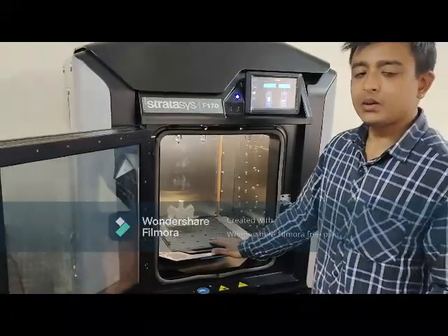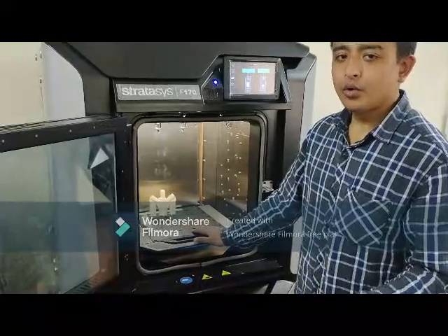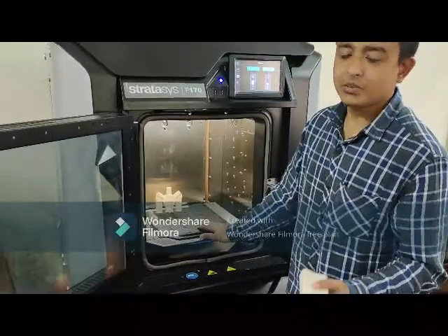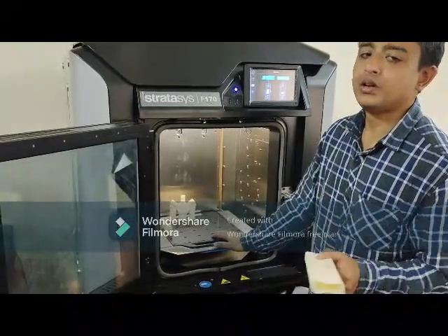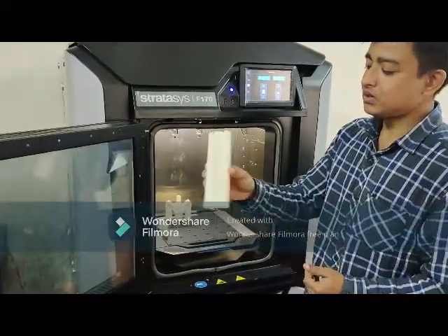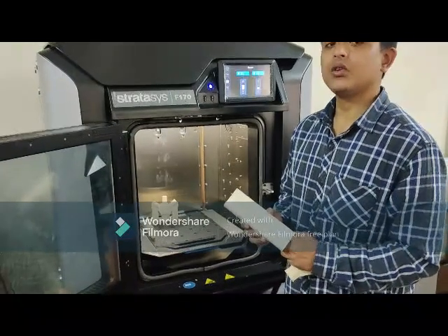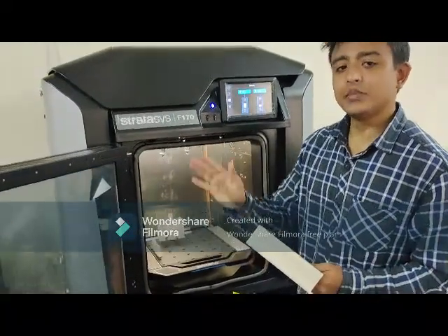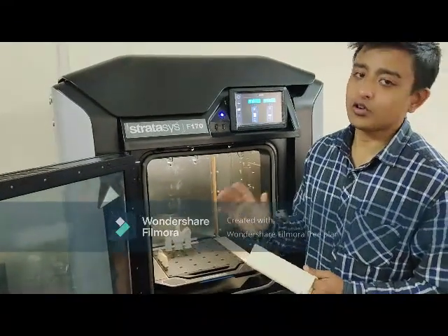After the completion of first cycle, when it is printing for the second cycle, the flow rate may not be 100%, it may be 20%, 30%. The amount of material flowing may not be proper. So to check this thing, we have this kind of thing, that is purge tower. So the purge tower is also taking care of this thing, that the flow rate is maintained constant or not, so that the amount of material we are receiving is correct or not.